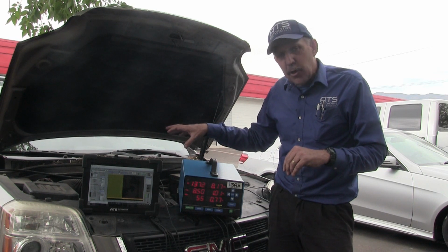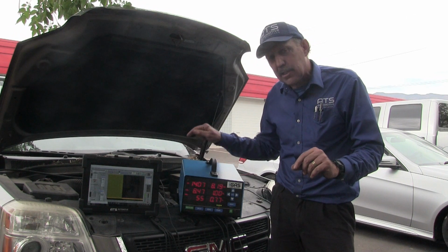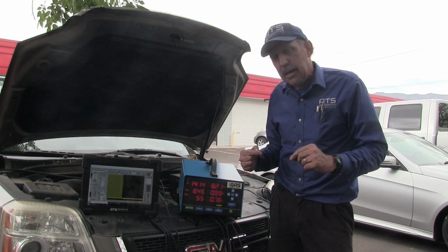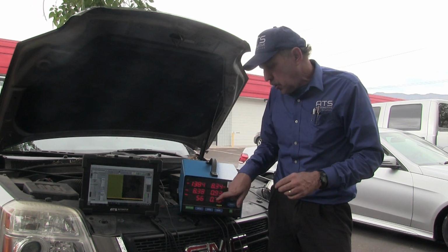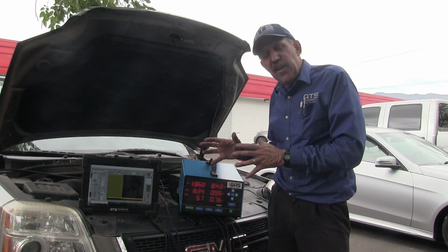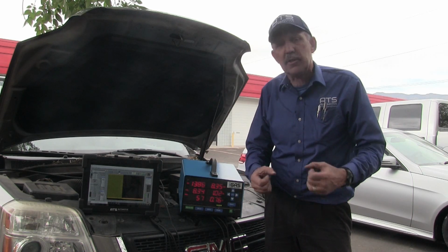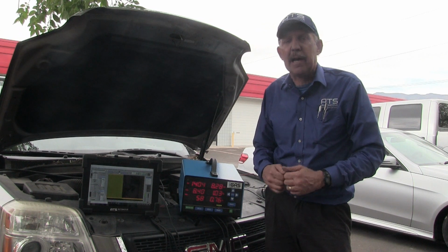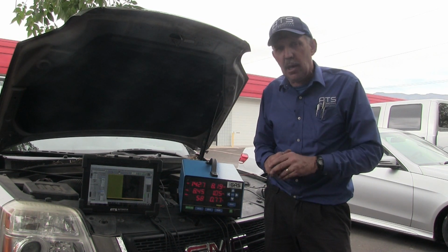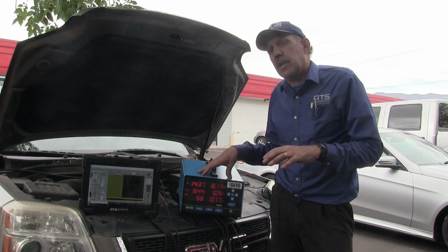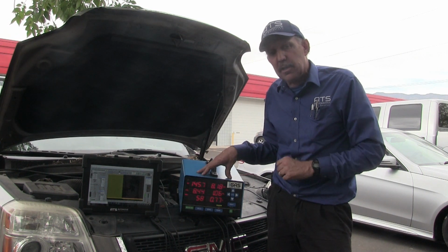If I've got 30–40% trim and I've got a lambda of 1, the trim corrected the problem and it did the right thing. If I'm adding 20–30% trim and the lambda is way too rich or way too lean, the feedback controls something's wrong with either the MAF sensor, the O2 sensor, but you've got something wrong with the feedback. In this car, we already know that that feedback circuit is being loaded. Now that I've showed you how to use your gas analyzer, let me show you how we're going to find out which component is loading the circuit.